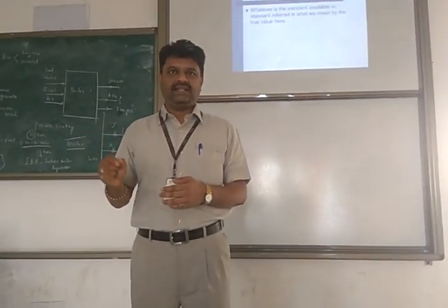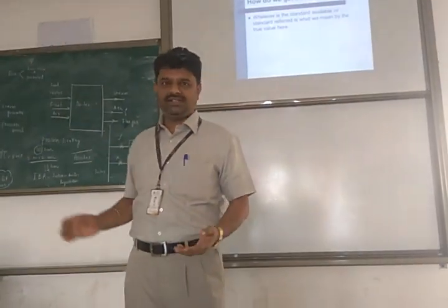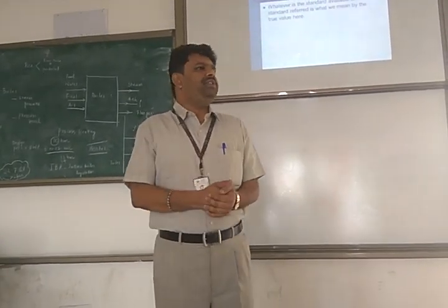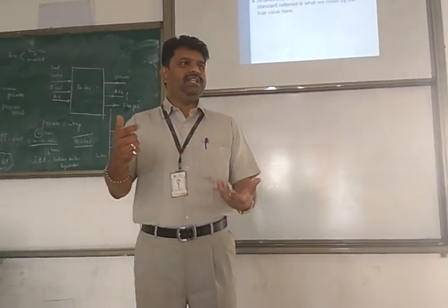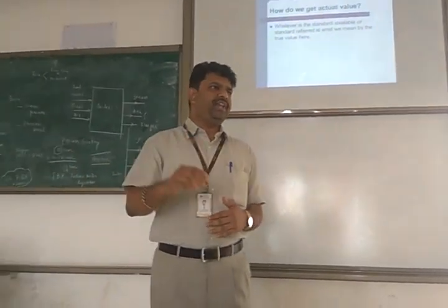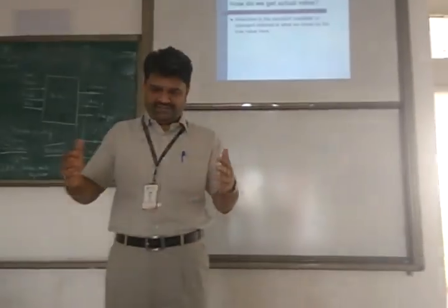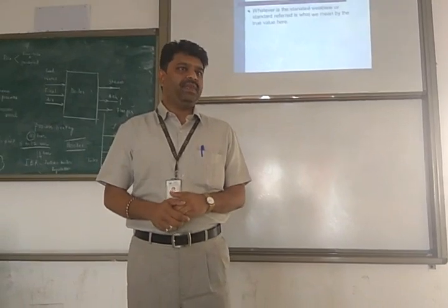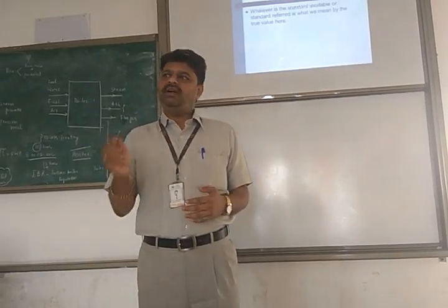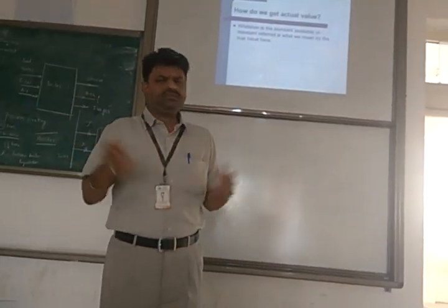You go to automobile components, where two digits of information after the decimal point are enough. For most automobile components, the fans, the cycles, the bikes, cars, any household engineering components, I'm able to do it with either 2 digits or 3 digits of data after the decimal point. For more sophisticated engineering, maybe aerospace or precision engineering, it is 4 digits or 5 digits after the decimal point. I'm able to do the intended function if I can measure the component dimensions to 4 or 5 digits accuracy.